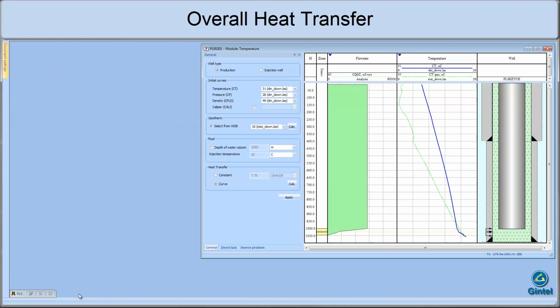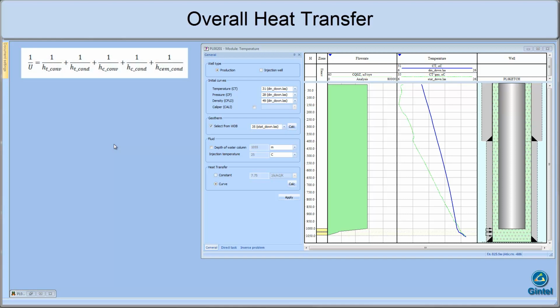Now, let's look more closely at the U value in the first formula, which is also called a steady-state overall heat transfer coefficient. For this purpose, we will consider a gas production well, where we see a typical production string with tubing pipe and casing and cement around the casing inside a drill hole. We will follow the procedure to calculate a U value. The U value is given by a formula of the sum of local heat transfer coefficients, where HTconv is the local